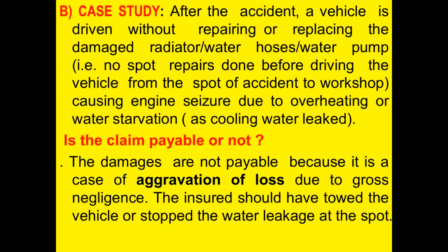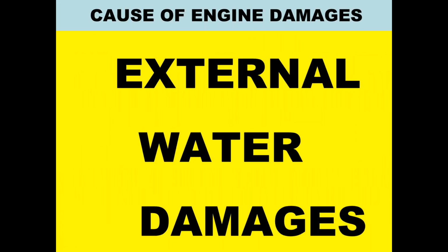Another case: after the accident, the vehicle is driven without repairing or replacing the damaged radiator, water hoses, or water pump. No spot repairs are done before driving the vehicle from the spot of accident to the workshop, causing engine seizure due to overheating or water starvation as the cooling water leaks. Is the claim payable or not? The damages are not payable because it is a case of aggravation of loss due to gross negligence. The insured should have towed the vehicle or stopped the water leakage at the spot.